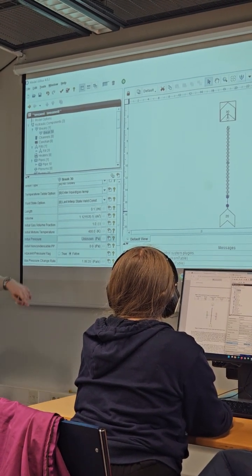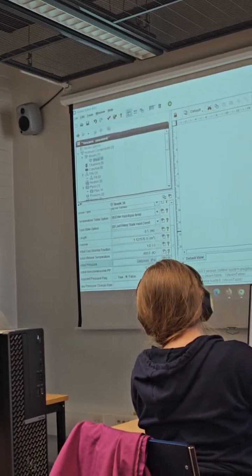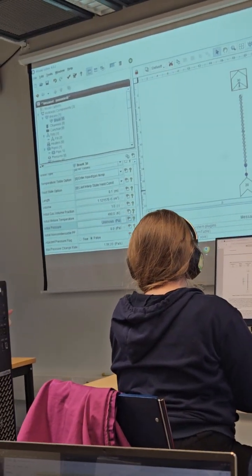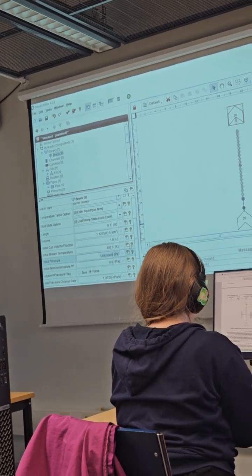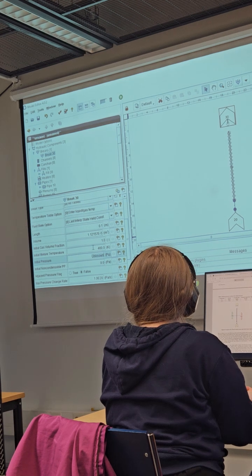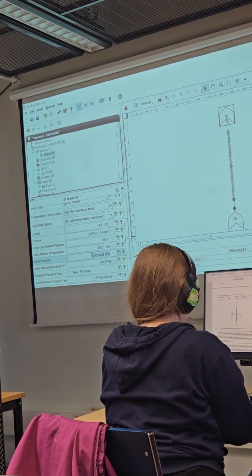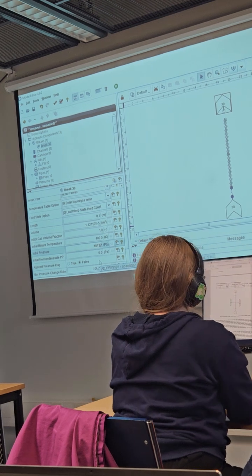Since we have a cross flow pipe of the vapor, while we don't have any coolant inside. Our coolant is vapor. It is quite a poor coolant with a low heat transfer coefficient. So we can define it as 400, and the initial pressure is also atmospheric, 101,325.